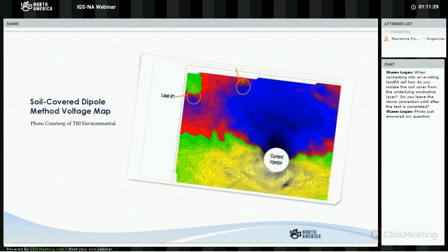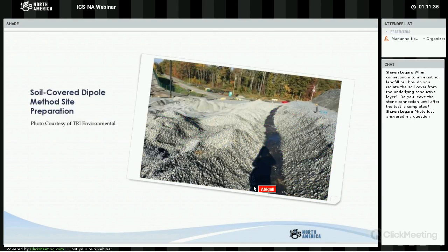Yes. So even along the tie-in, I like the landfill to look like this. So you do your geosynthetics tie-in, and then usually, you can actually see it here, they usually leave like a windrow of cover material along that edge. So after we do the testing, you could just push that material into that isolation trench when you're done. Some people get really crazy about it and they want us to arc test this strip of geomembrane to make sure there's no holes in there before we cover it, and that's fine, but usually people just feel comfortable that there's no leaks there and they carefully push the material in.